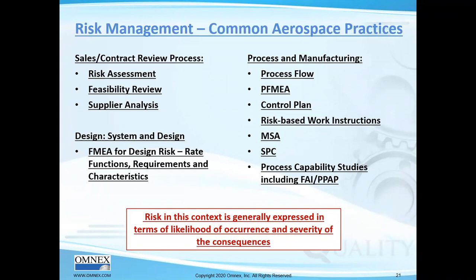Okay? And also for your process manufacturing, most companies already have some sort of a process flow. It's either in a flow chart or a procedure. It's usually documented somewhere on how things flow from start to finish. All AS9145 does is kind of put that into a systematic, easy to follow manner that's step by step. That obviously helps you identify more risks and opportunities and controls that need to be in place for your actual processes to make sure you're getting good parts every time, all the time.